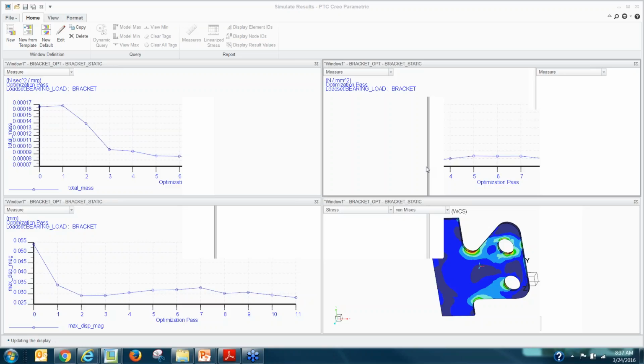Can you set up an oscillating pressure or temperature in Simulate? Is it possible to determine a combined thermal structural stress for that scenario? Yes, yes. So oscillating pressure: once you apply the pressure load, like I said earlier, Kyle, you're asking pretty much the same question, you would have to add it as a load set because we couldn't do that in Creo 2. If you recollect, in Creo 3 we are able to add multiple load sets in fatigue. That's how you would add an oscillating pressure.